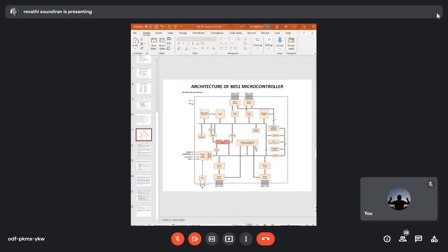The serial buffer register is byte addressable, that is, you can use it as an 8-bit register only. But the serial control register is byte or bit addressable. You can access each bit in that register or access the whole 8-bit data. Both are possible.